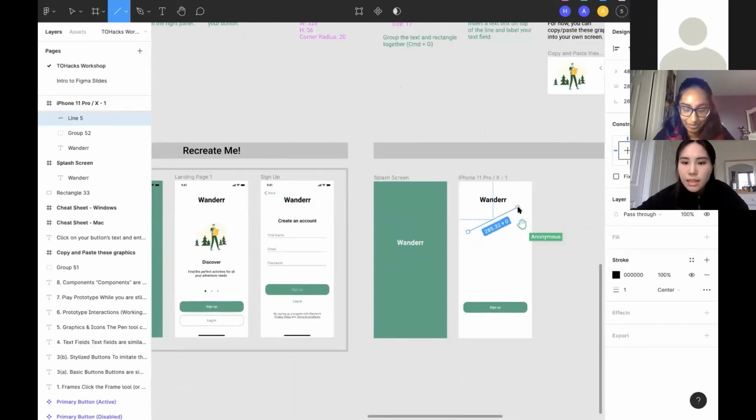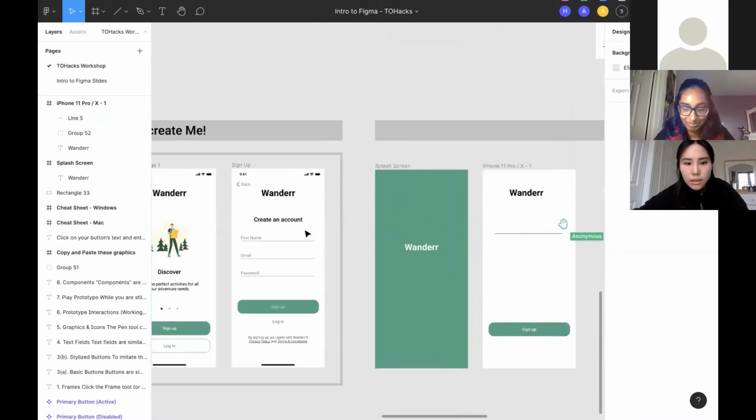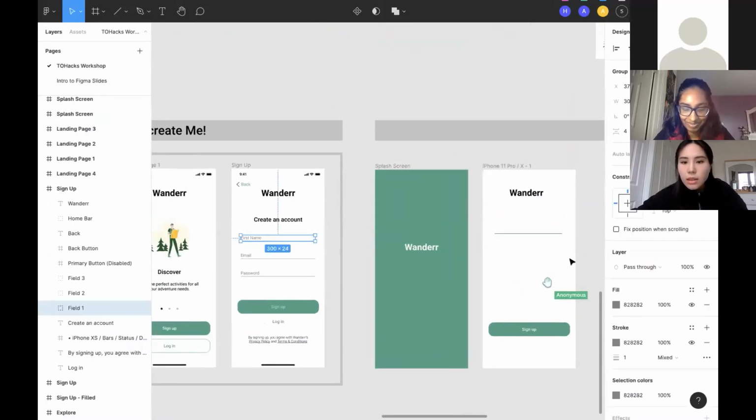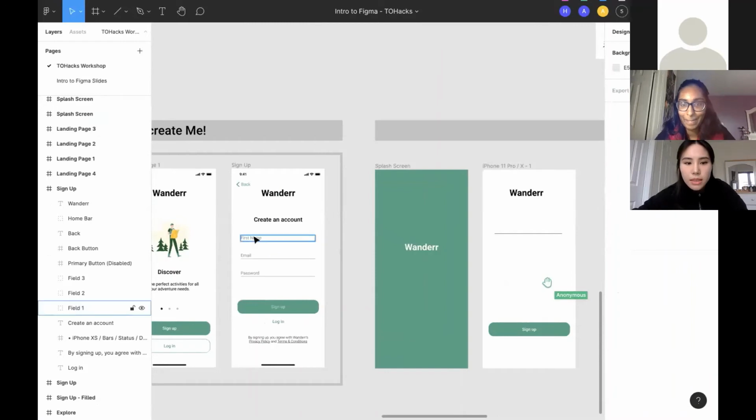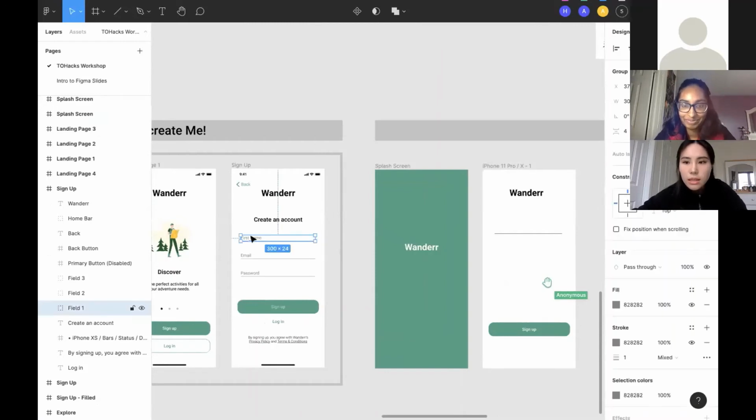And then if you just create a line like this, the angle is kind of very flexible, but I want it to snap at 0. So to snap it at 0, I'm going to hold shift. So by holding shift, the line I make is going to snap to its nearest 45 degrees angle, like that. Okay. So I want the line to be the same length. So I'm going to click this and see the width.